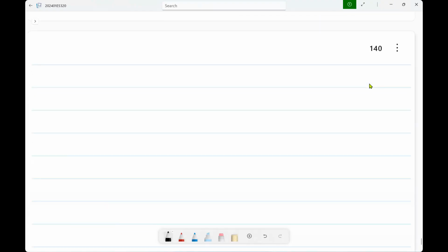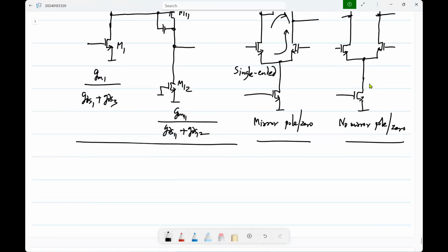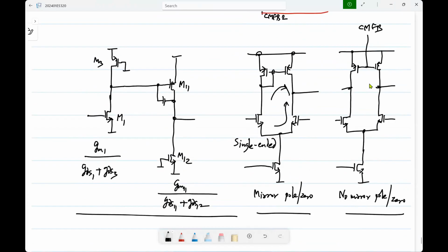Now, all the other things, basically swing limits and so on, you can calculate. There is nothing particularly special about it. If you know the bias points and you know the total voltages, you find the thresholds at which the transistor goes out of the desired region, either into the triode region or the cutoff, and find the swing limit. So that itself is nothing special.